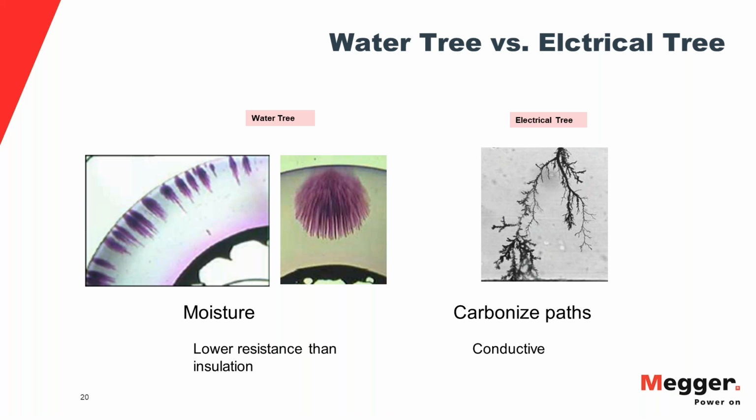And actually, there's a few utilities in the US that have a disqualification criteria when they do the VLF test, because only with the cosine rectangular VLF, and they have a cosine rectangular test set, only with that technology can you also record the leakage current during the acceptance test. When the cable hits a threshold, a number that they have found by experience or by a study that they conducted, they will disqualify the circuit as well, even though it did not directly fault during the test. But the leakage current is so high that there is a low resistive problem imminent.